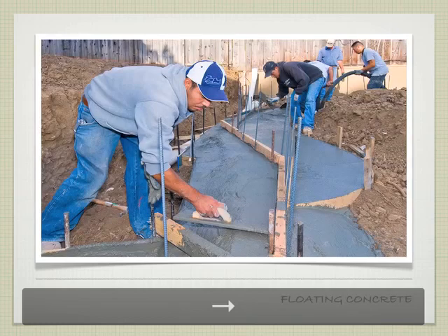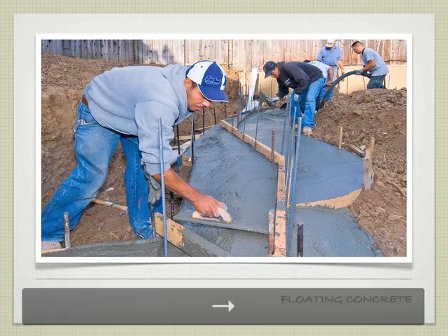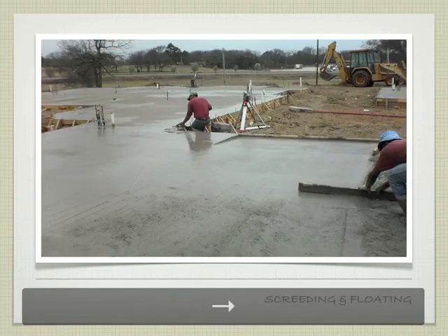So you have to be somewhat aware that your finish is never going to be quite as good around those areas. You can do the floating at a much smaller scale with a hand float instead of one of the big floats. Obviously, this is at a smaller scale, a little bit less accurate, a little bit more freeform, but the concept is still there.